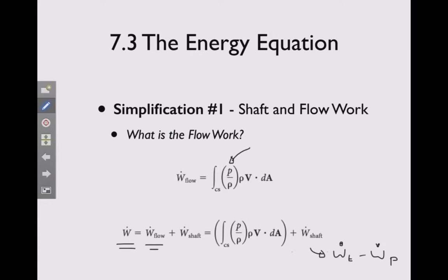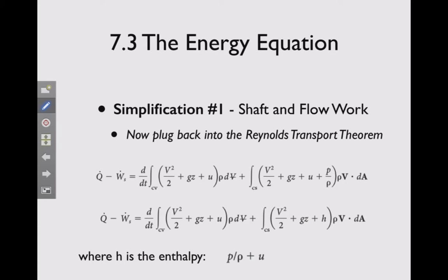So we're going to have to carry along this pressure term, and that's what's going to give us the pressure term that makes the energy equation look like the Bernoulli equation. When we plug all this back in, you can see that we're still subtracting out the work, but this is only the shaft work now, and the flow work has been added over here into the control surface, right here.